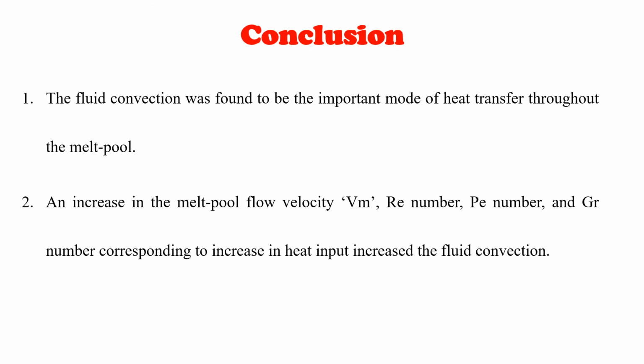Now, moving to the conclusion, fluid convection was found to be an important mode of heat transfer throughout the melt pool. Next, an increase in melt pool flow velocity, Reynolds number, Peclet number, and Grashof number corresponding to an increase in heat input is observed to increase this fluid convection.